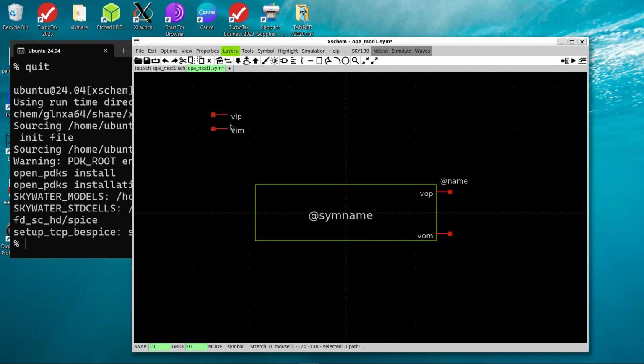No, you just click and drag the area you want to select. So if you left click, hold and drag it. But yeah, if you select the whole thing, you want to maybe just select. So you can also select by one with shift. So for example, if it is too close to the corner where it is selecting the entire symbol, you can select the pin and select the name, shift and select the name, and then press M and move it out.